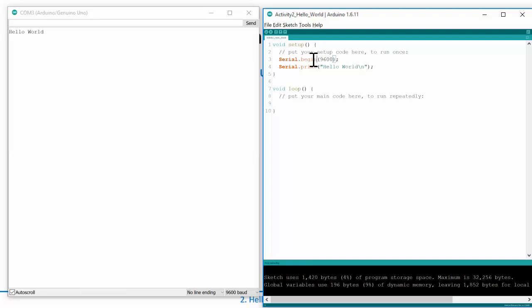In this situation, what this does is it sets up the baud rate. It sets up the UART communication down the USB to the Arduino, and the 9600 is the baud rate, which is the speed at which the serial bit stream is sent. When you do that, the serial monitor works. That's all you have to do to get a serial connection to talk to the Arduino using the USB cable, and it will communicate back and forth. And so you can see how easy it is to program, because it's abstracted all the stuff that it just did for you. So you just put that in there and bam, it works.